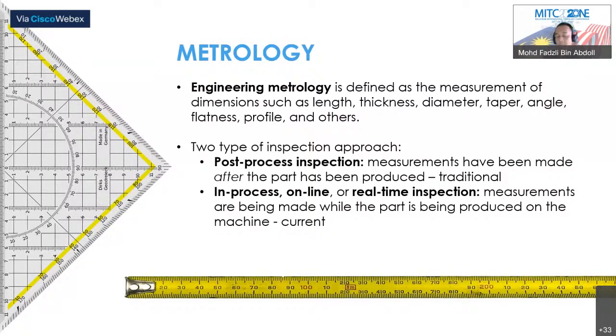Macam contoh yang tadi lah, bila kita produce a part using a 3D printer, some of the part need to have a post-processing, especially for the surface finish lah. It means that we need to abrade the surface in order to get the smoother, smaller surface roughness.